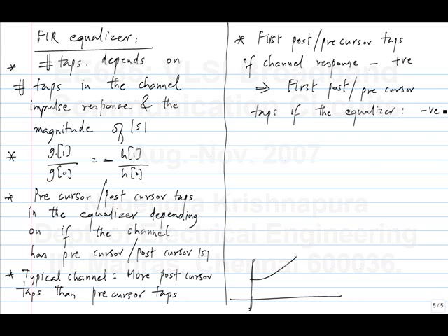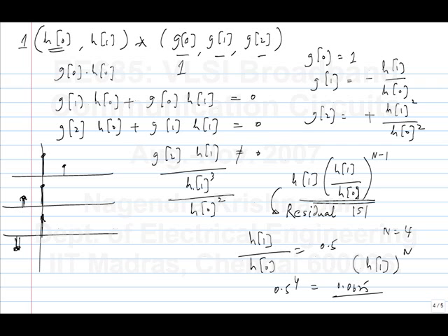So if you have more taps, you will have more terms to deal with, and you will have more equations and more variables. Here we always had two terms adding up, so we could just by inspection write down these terms. If you have H0, H1, H2, H3 and so on, these will have 4 terms, let's say 4 non-zero terms. So you'll need 4 simultaneous equations to solve for G. Okay, but you can solve it nonetheless. There's nothing complicated about it.